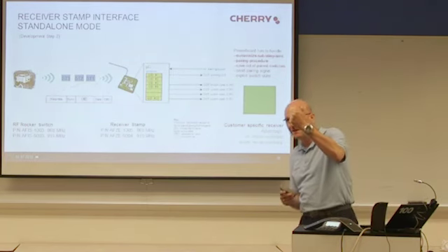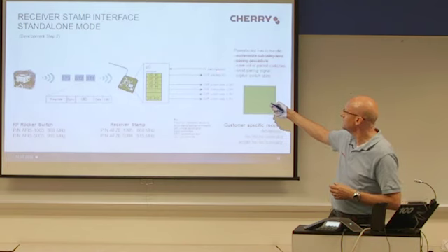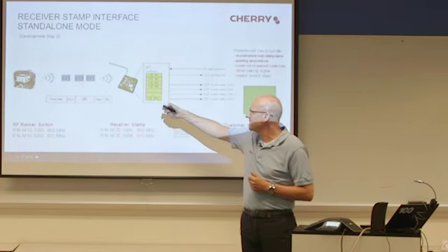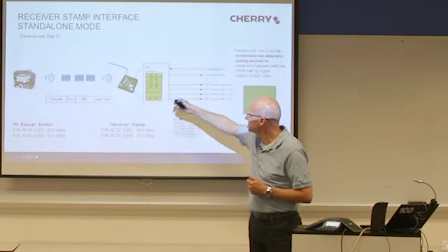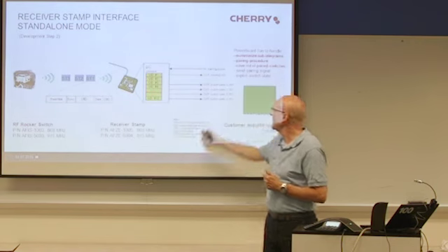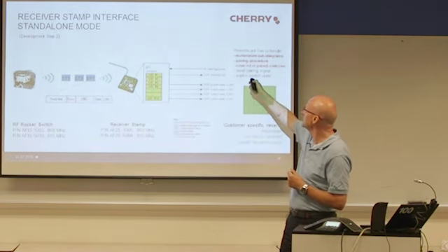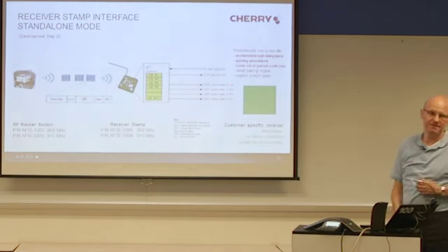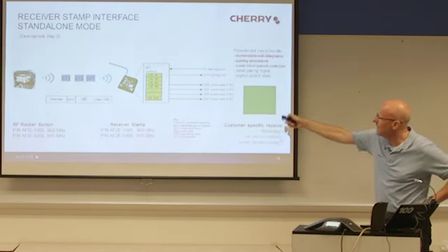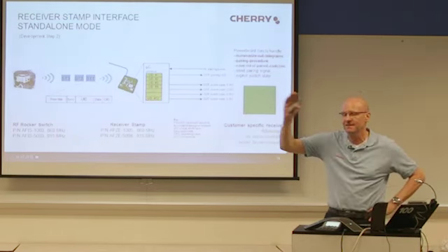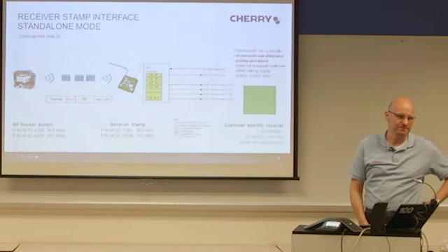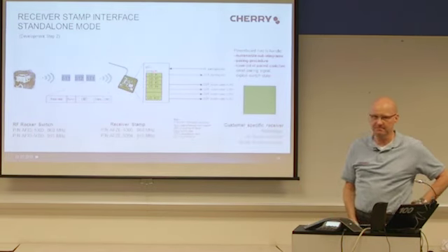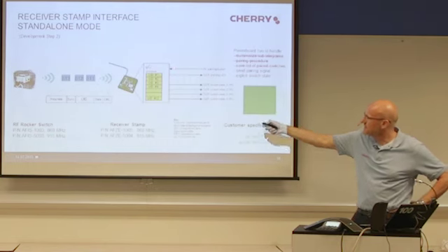So I press this short button on my bulb, and then my bulb sends to the stamp that pairing mode is active. And then the RF stamp saves all the pressed switches in its phone book, and then, for example, the bulb says pairing mode is off, and then it's off again. But the power board has to handle or initiate the pairing process. But all the unique IDs and all this is handled on the RF stamp. And this is the big advantage.